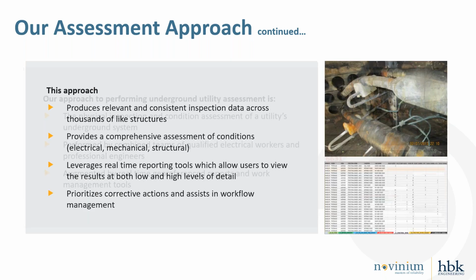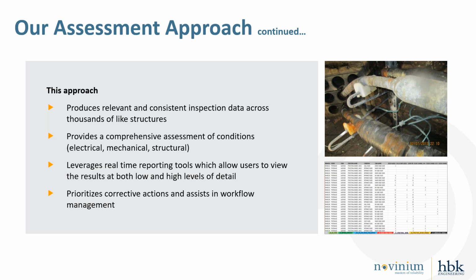The next consideration is that accessing each structure can take considerable effort, from traffic control setup to dewatering and potential full environmental cleanout. To maximize on the return of data for that investment of gaining access to that manhole, our engineer captures many other significant data points on the manhole outside of the electrical system. So during an assessment, our engineer will capture environmental data, structural data, and mechanical data, and make the most of that one single visit to limit the need for future visits for any repair work that is required.